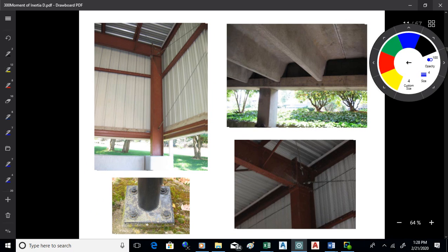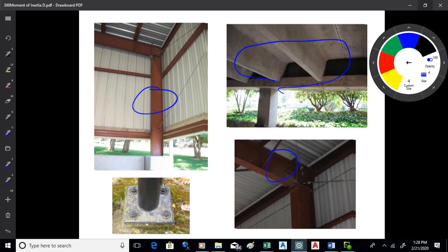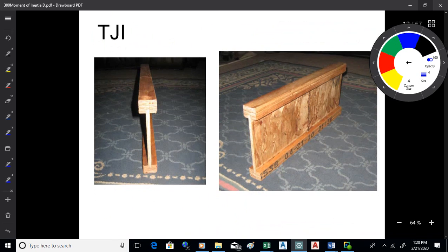Okay. So there's a few structural applications there. There's a column that's made out of an I-beam. Here's another I-beam itself right there. Here's a double T-beam made out of precast concrete. That's what we used a lot on this campus here. That's what the roofs are made out of. Either that or these kind of waffle kind of patterns that you might see. Here's a column made out of a tube. Okay. There's a square concrete column right there. So there's kind of the standard shapes, you know, as they're used.